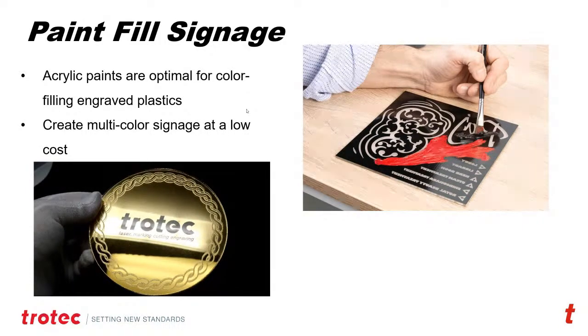You'd want to stay away from alcohol-based paints with plastic. Anytime you use alcohol with acrylic, it'll actually cause the acrylic to crack. So stay away from alcohol-based paints or cleaners when it comes to acrylics.